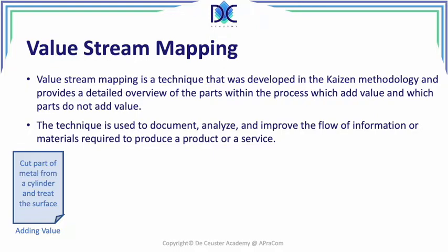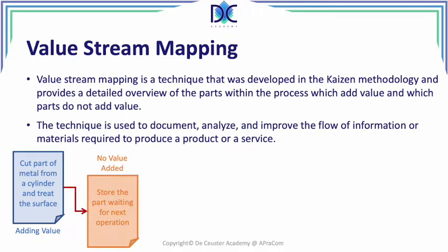A value stream map can look at this. First of all, we have a first operation. We cut a part of metal from a cylinder and treat the surface. Then we have a first part, we added value. Now we store that part waiting for a next operation. Here we don't add value, but it means that we're moving it somewhere. There's something can happen with it. So this is a non-value adding step.